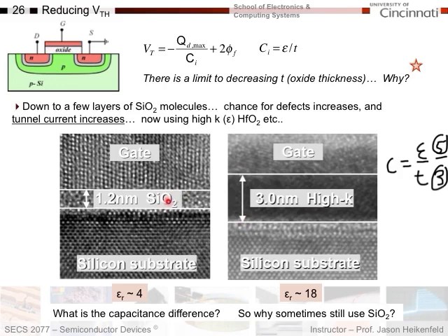When people went from this to this, it was very controversial. The reason why is that when you make these just few nanometer thick dielectrics, imagine a computer chip. If there was one defect here, one little crack or something like that, then the metal could penetrate through here, short to the silicon. If one transistor shorts out, the entire computer chip is shot, right?